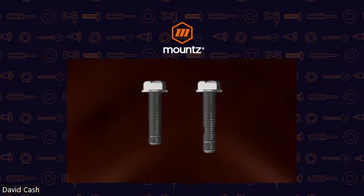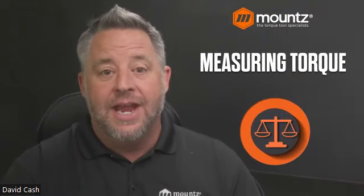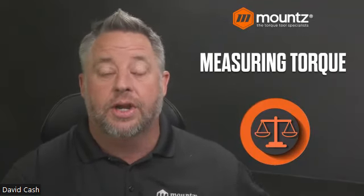Obviously, the elongation and the threads that have been narrowed at the point of the fastener there, that is showing us the actual deformation, and that fastener is then in the plastic region and is susceptible to breakage. So when we are looking at actual torque, how do we measure torque?